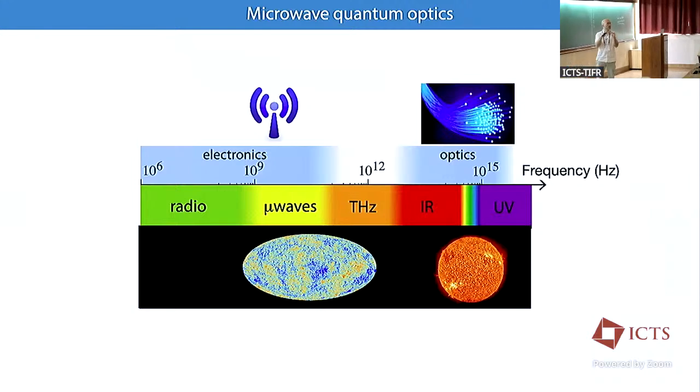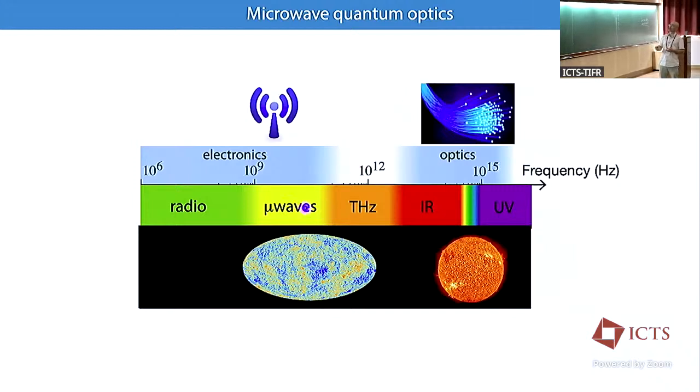So this sets a limit to below 10 gigahertz if we stick to using this kind of superconducting elements. And if you look at the typical values of epsilon naught and mu naught, you get that the right order of magnitude to get gigahertz frequencies is to have geometrical objects of millimetric extent. So this is very easy to fabricate, millimeters. We can do it with very conventional nanofabrication equipment. And so basically this gigahertz domain lives in the realm of electronics. After that there's the terahertz gap where we have very limited tools, and then there's the optical regime.